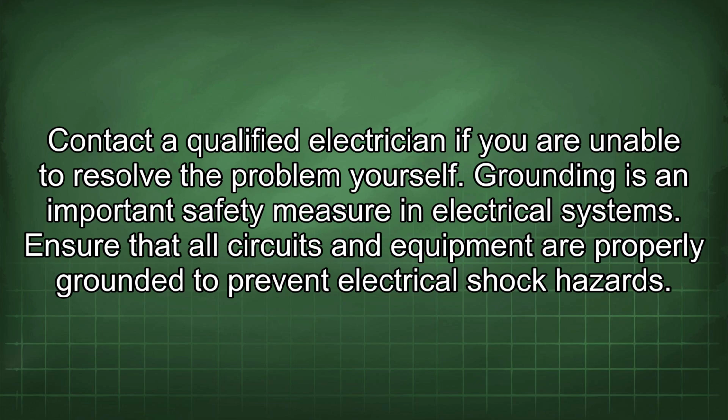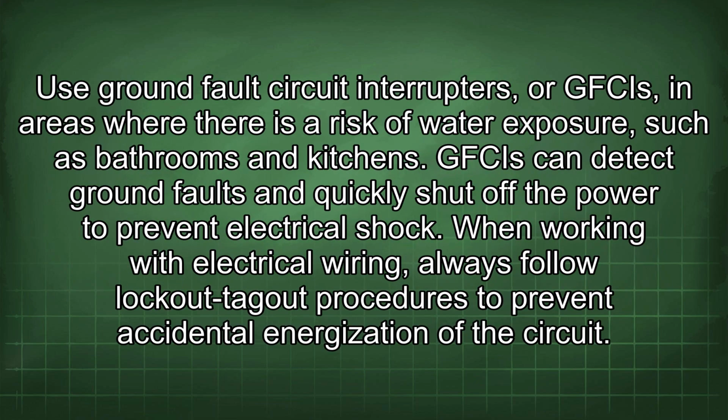Grounding is an important safety measure in electrical systems. Ensure that all circuits and equipment are properly grounded to prevent electrical shock hazards. Use ground fault circuit interrupters, or GFCIs, in areas where there is a risk of water exposure, such as bathrooms and kitchens. GFCIs can detect ground faults and quickly shut off the power to prevent electrical shock.